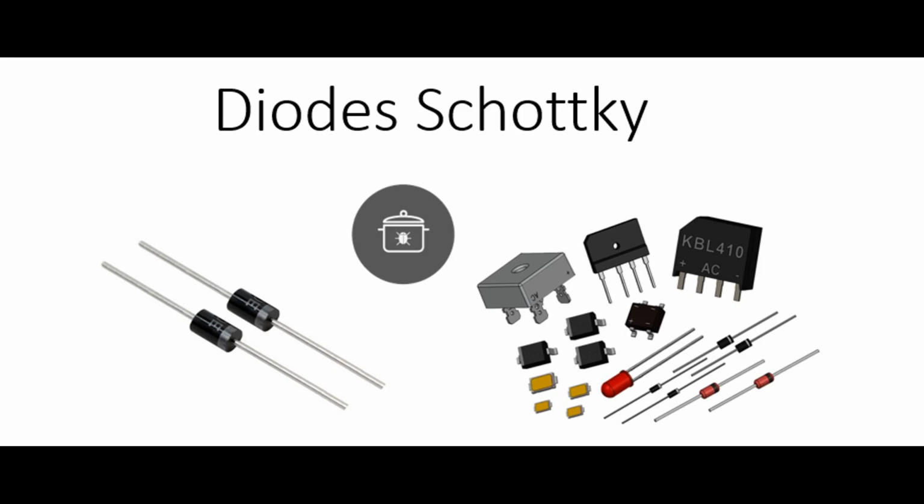input signals at different frequencies and produce an output signal that contains various frequency components, including the sum and difference frequencies of the inputs. The main function of mixers is frequency conversion, which is a fundamental operation in RF and microwave systems. They are commonly used in frequency translation. In RF communication systems, mixers are used to convert high-frequency signals to lower intermediate frequencies, for further processing and amplification.